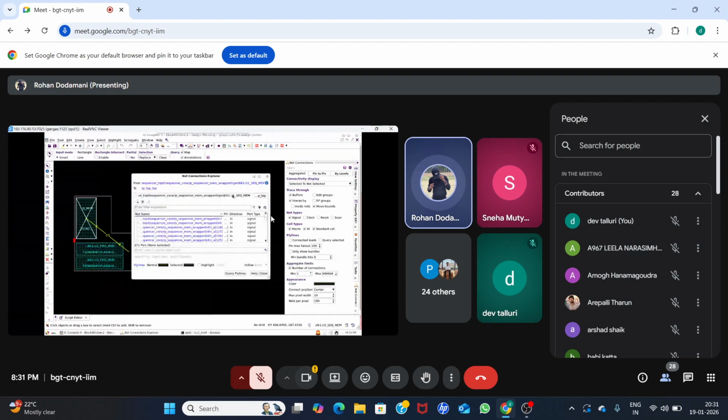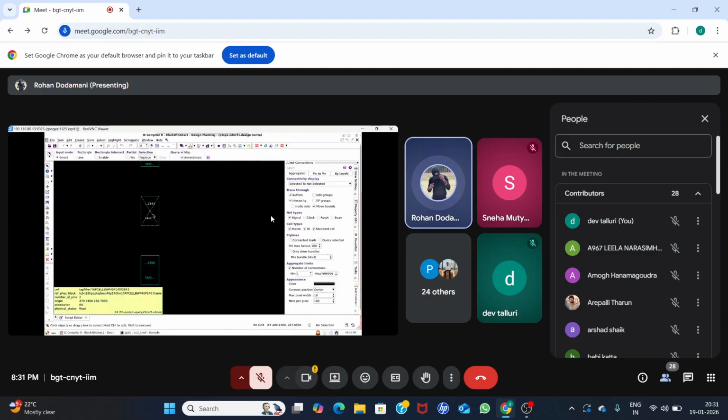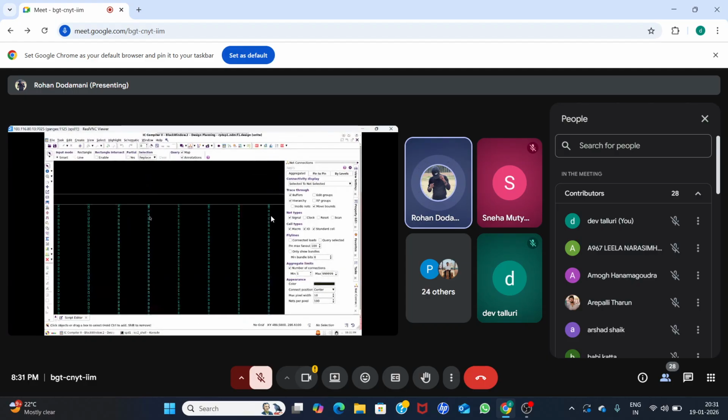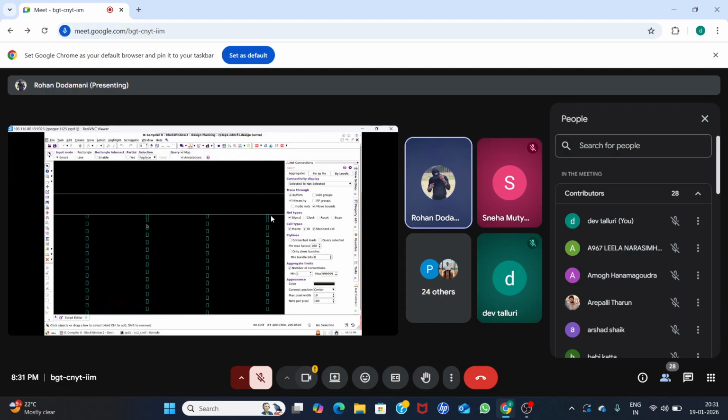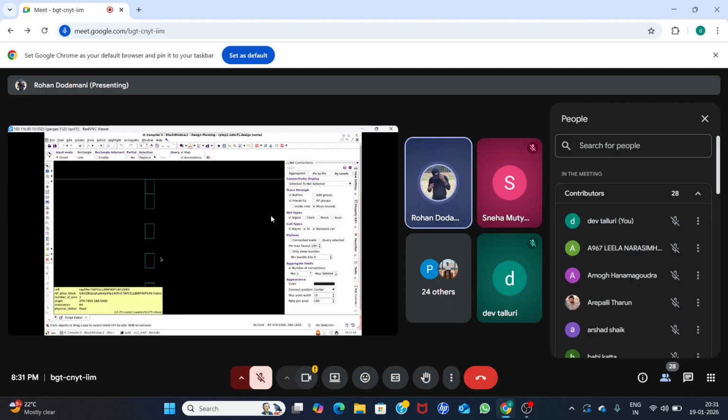And whatever is inside that you are seeing now, these are the tap cells, we call them well tap cells. Why are we adding these well tap cells? I told you, for the prevention of latch up issue. In between one tap to another tap we give some space, here to here.